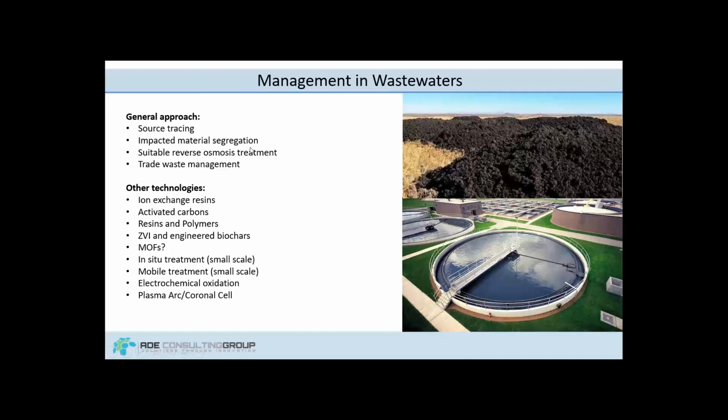Impacted material segregation applies to biosolids, so finding out if we do have, through our monitoring programs, an excess of PFAS at a given time, to separate out the biosolids generated during that process. And there's a number of other removal techniques, including reverse osmosis. These are expensive techniques, and with the volumes of water that are generated typically by wastewater treatment plants, are not often practical. There's a great number of technologies that are being investigated or are currently being applied.